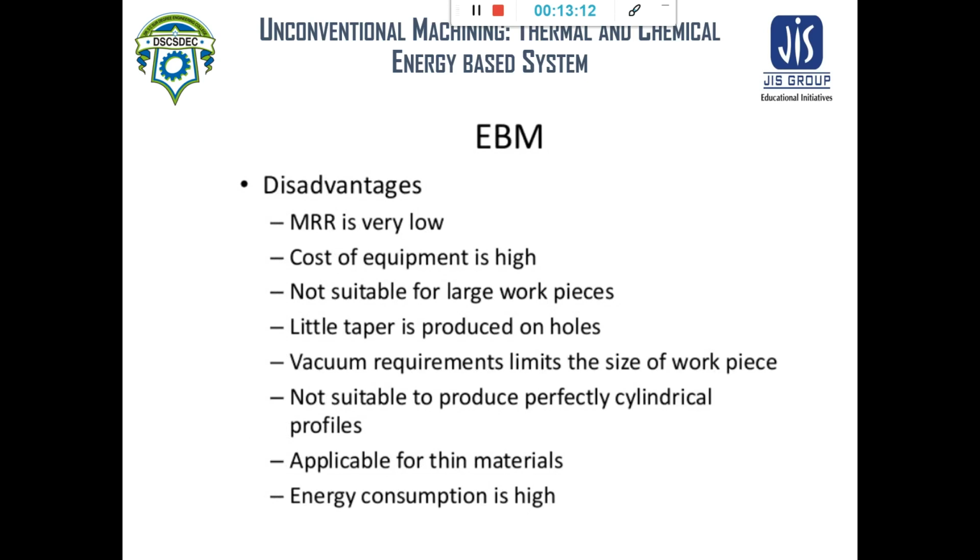Disadvantages: MRR is very low. The cost of the equipment is high. This process is not suitable for large workpieces. A little taper is produced on the whole. The vacuum requirement limits the size of the workpiece. This process is not suitable for producing perfectly cylindrical profiles.